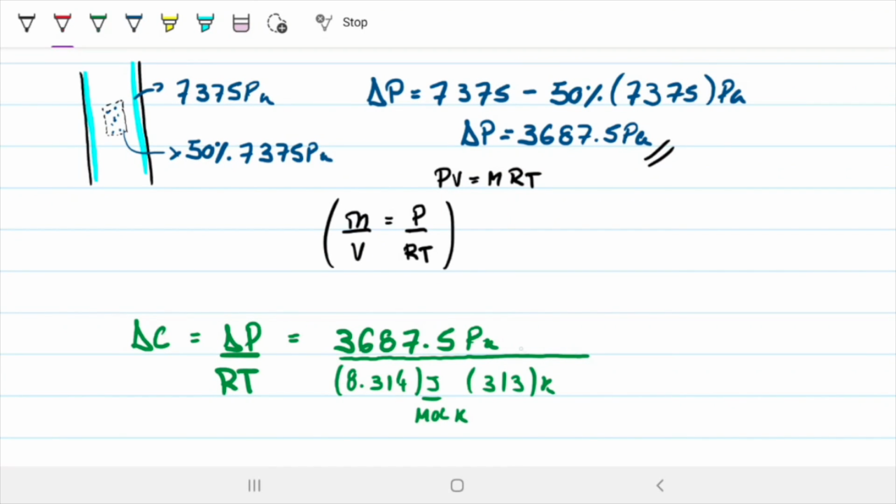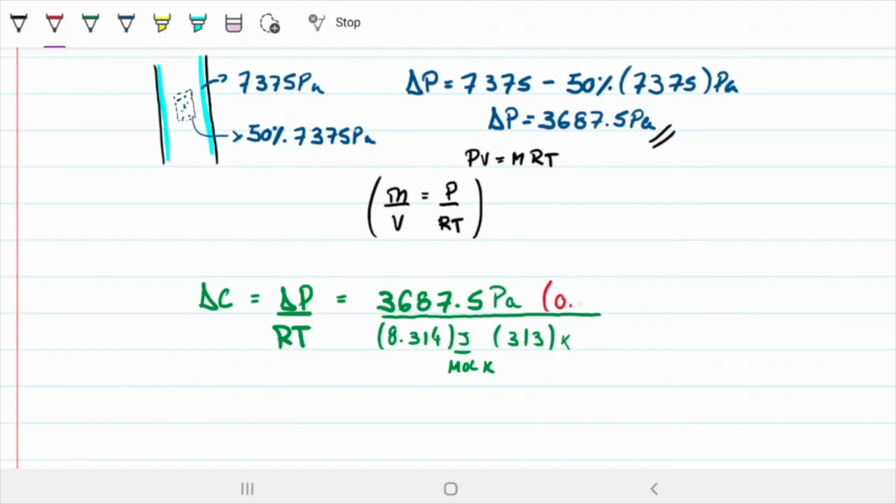we can do the same trick we did before, which is multiply the whole thing by the molecular weight, which in this case is 0.018 kilograms per mole of water. And this can be tricky because remember that we are looking at the diffusivity of water and air, right?